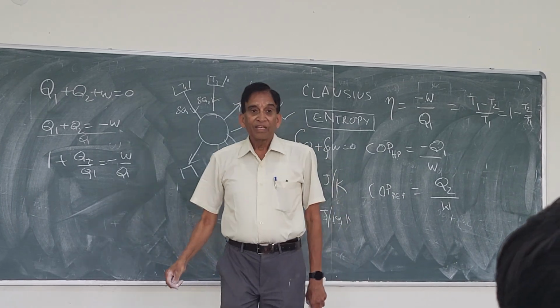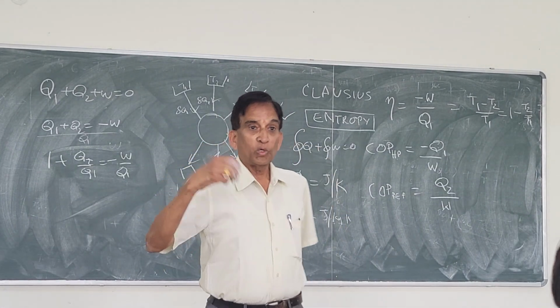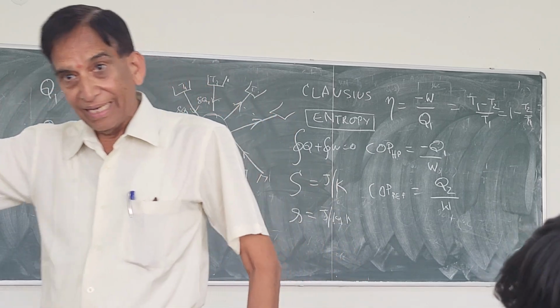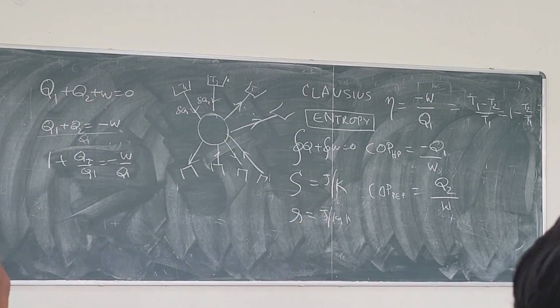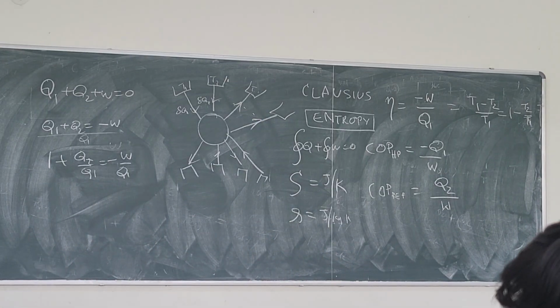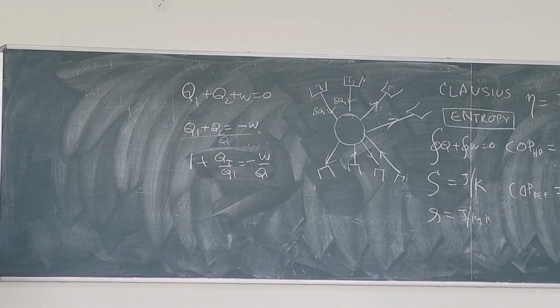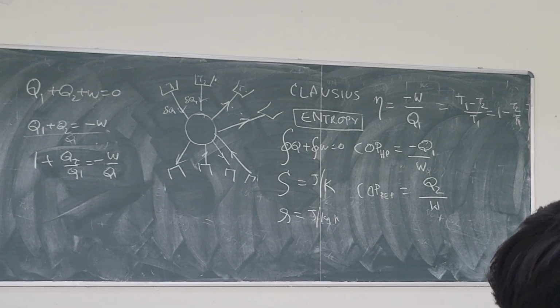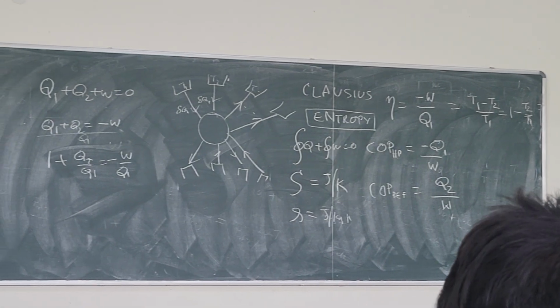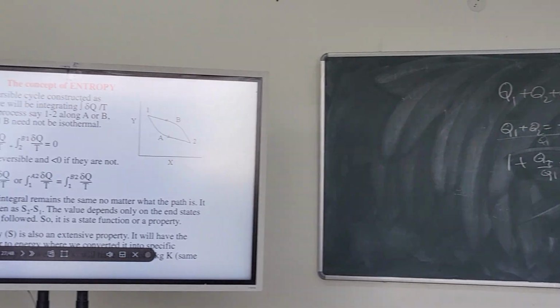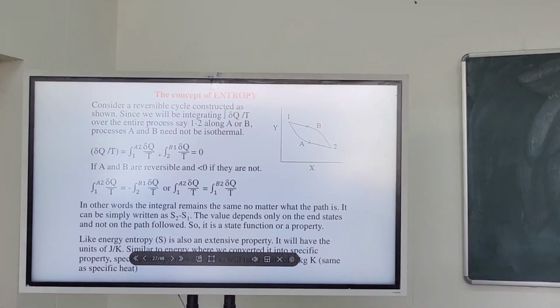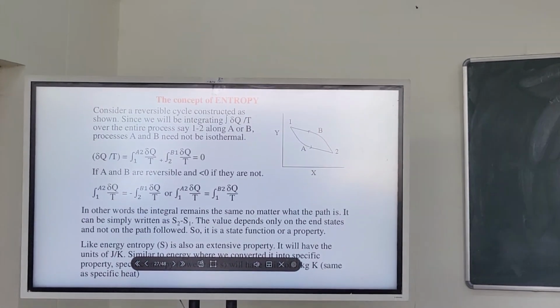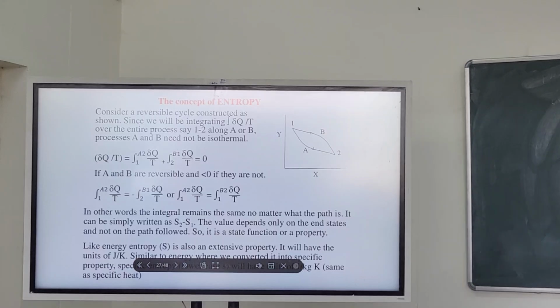Right, remember? We had capital V for volume, and specific volume is meter cube per kg. We said internal energy, so many kilojoules, or if it is lower case u, it is kilojoules per kg. Enthalpy, if it is capital H, it is so many kilojoules; if it is per unit mass, specific enthalpy is kilojoules per kg. What is listed in your steam tables is everything as specific volume, specific internal energy, lower case u, specific enthalpy, and also specific entropy.